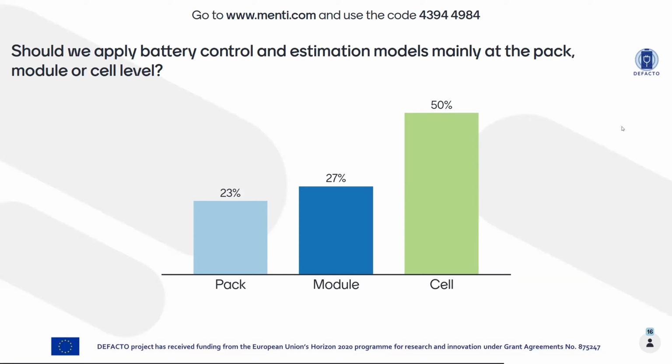But then in terms of voltage sensing, it's really down to where that voltage is being sensed and whether you've got access to that information. I think one of the problems is, especially for large grid storage systems, you might have tens of thousands of cells in the system, and it's not really practical to get all of the individual voltage measurements and pass them up to the BMS or EMS.